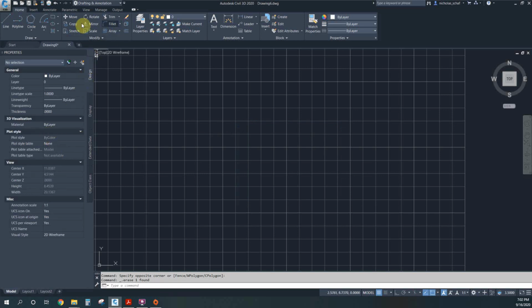The next thing that we're going to talk about is polygons. So polygons, right next to the rectangle button, if you press the down arrow, that will bring up 2 options. One you've already seen, rectangle. Next one is polygon. So it asks you to select number of sides. This is a little odd because it allows you to draw a square, which technically, yes, is a polygon, but if there's already a rectangle, then why do you need it? But whatever. Autodesk made it. I don't ask questions. I just follow the rules.